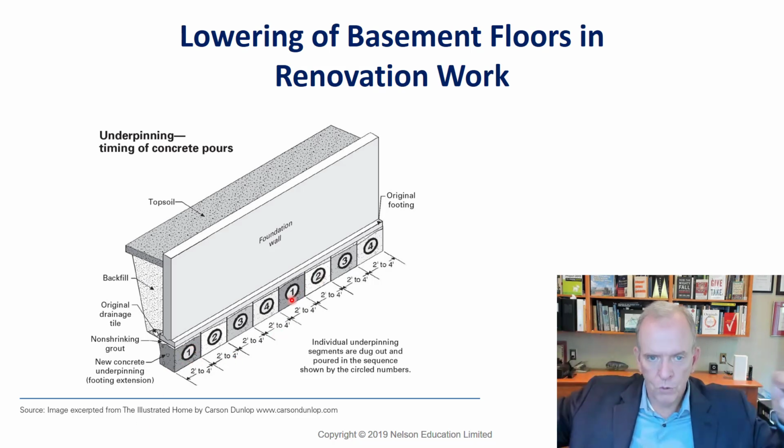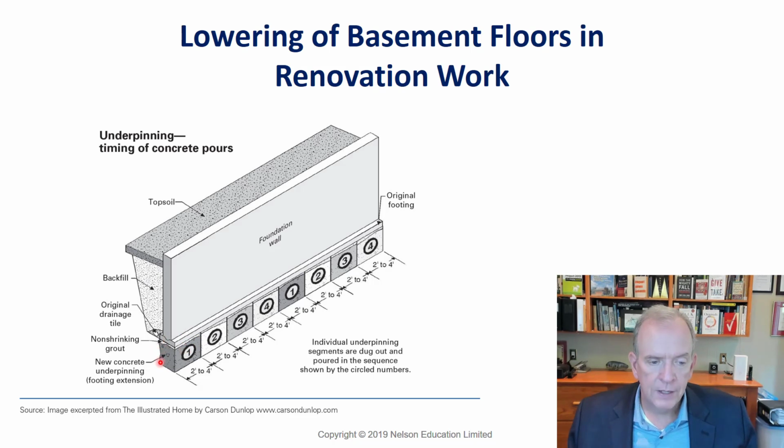So that would go all the way around the house. Let's say if we're lowering the entire basement, you would excavate all the number ones. And what you would do is you would typically chop this part of the footing off, and you would form this up with formwork, and they would all be excavated underneath the footing. So you do this usually by hand, so it's very labor intensive. And then you form that up and you fill concrete in all the number ones.